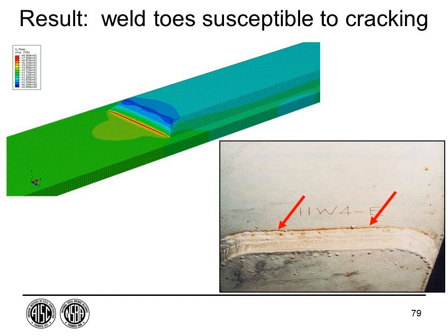And so when we do fracture mechanics checks, when we do fitness for service, we're doing a project for NCHRP, and that's how we're doing it, is we're assuming that there's an initial defect of a certain size. How large can it be before it would be expected to grow, or how big can it be and not grow for a given stress range? Again, there's some assumptions in there that you have to be careful with, but that's using a fracture mechanics approach.